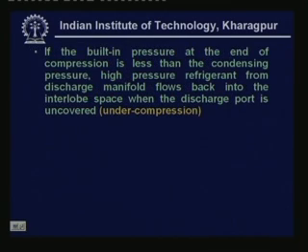If the built-in pressure at the end of the compression is less than the condensing pressure, high pressure refrigerant from the discharge manifold flows back into the interlobe space when the discharge port is uncovered. This is known as under compression.